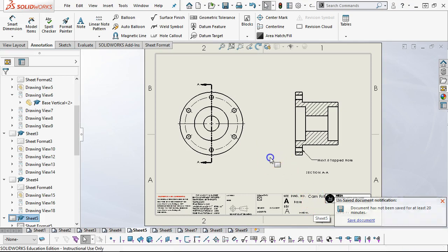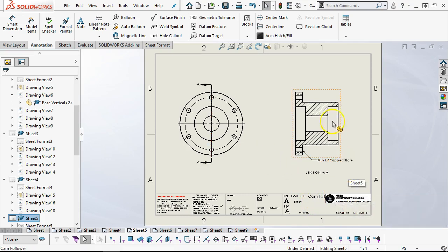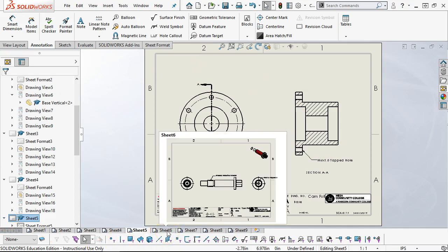Let's see, did we give that a full name? For the bearing housing, we want to look at having either positional tolerances for the two bearing faces, bearing cylinders, or we'd want to look at having runout where the first becomes a datum A, the second becomes a datum B, and then the rest of the geometry is in reference to the face, and then potentially the lead face would be a datum C. So that would give us a couple to work with.